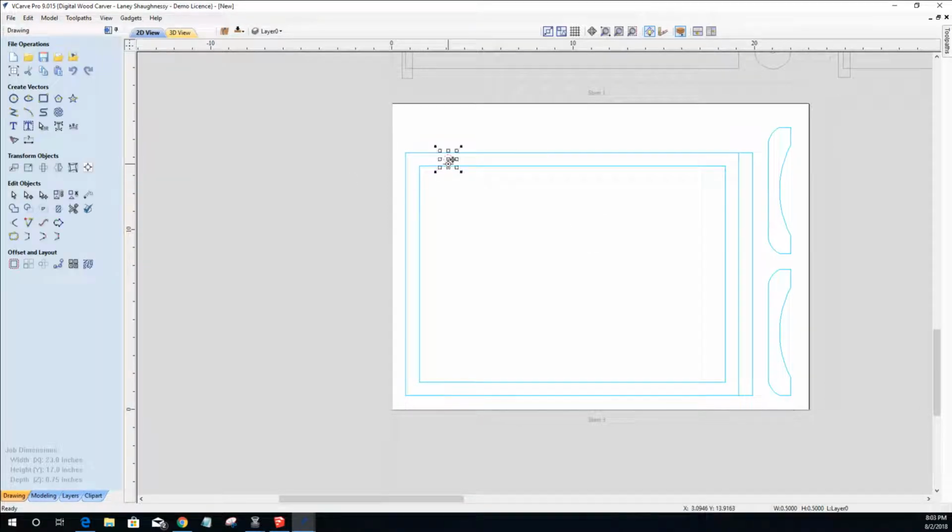So in the case of this, I want to select my vector, which is this guy right here. I want to double click on him, hold down my shift key and pull him out every little bit, so that my router bit can travel when it's doing the pocket cut between these 2 areas and get plenty of room to go past my profile cut to give me that nice clean cut.